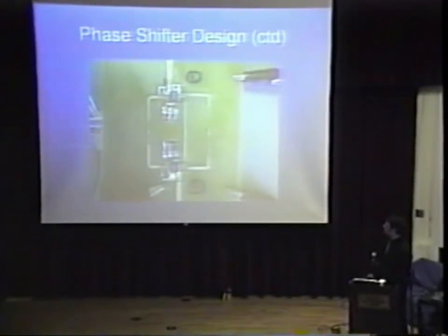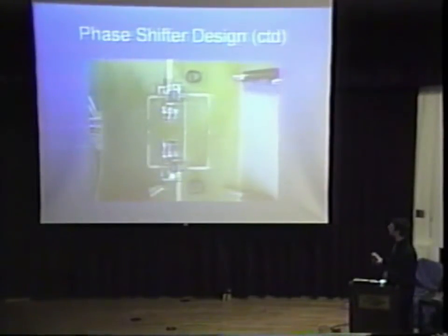This is a prototype of one of my phase shifters. This one delays the signal by 88 degrees. This one does by 43 degrees, and this is what they're referenced to in the center here. I used a switch by Skyworks. This is a gallium arsenide microwave switch, single pole four throw. I used some 100 picofarad DC blocking capacitors and some 50 ohm high frequency resistors right there. They're really small. These parts are 30 thousandths of an inch wide by 60 thousandths of an inch long.